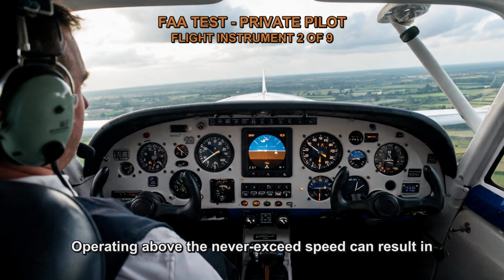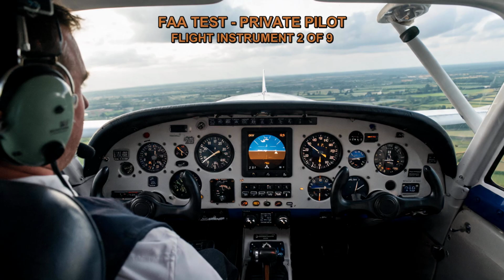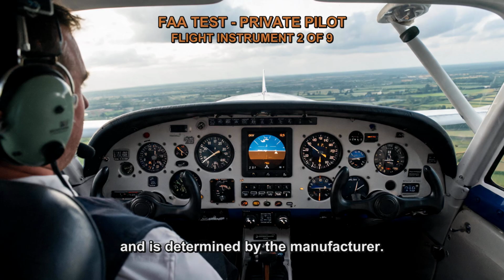Operating above the never exceed speed can result in structural damage or failure of the aircraft. The never exceed speed is specific to each aircraft and is determined by the manufacturer. It is typically indicated on the airspeed indicator by a red line or red arc.